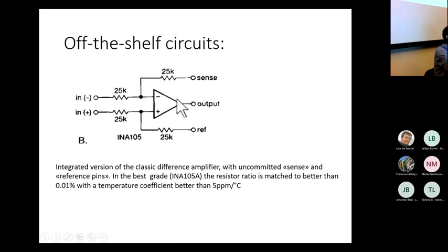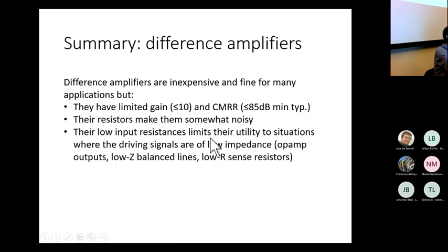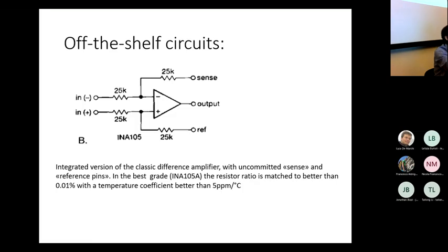This kind of difference amplifier, by the way, can also be connected in multiple different ways. But achieving such high precision can be complex, and there may be an alternative to that. Especially because even if we buy a circuit like this, we have the problem that maybe the minus R2 over R1 gain that we get in this case is not sufficient.